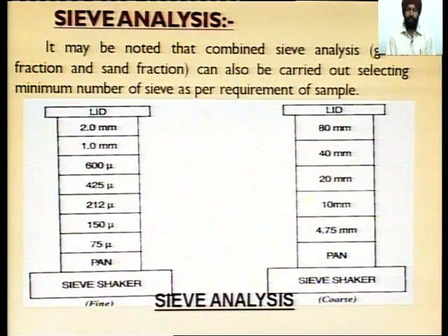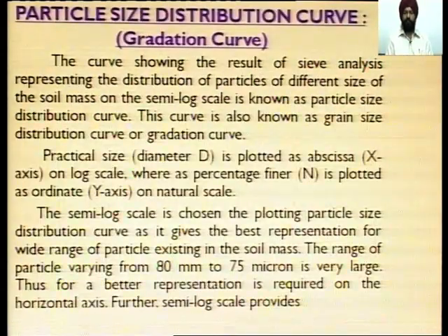It may be noted that combined sieve analysis, of gravel fraction and sand fraction, can also be carried out, selecting the minimum number of sieves as per the requirement of the sample. Next is after the sieve analysis. We know the percentage of the passing material in each sieve and the size of the sieve is also known, and then we have to plot the